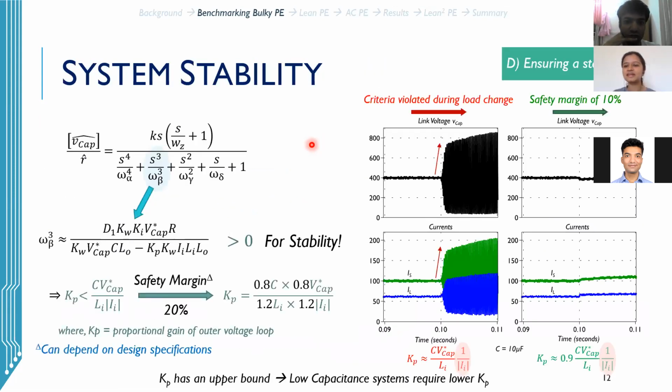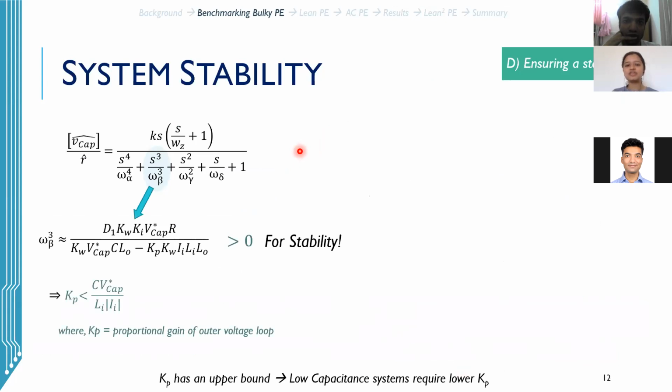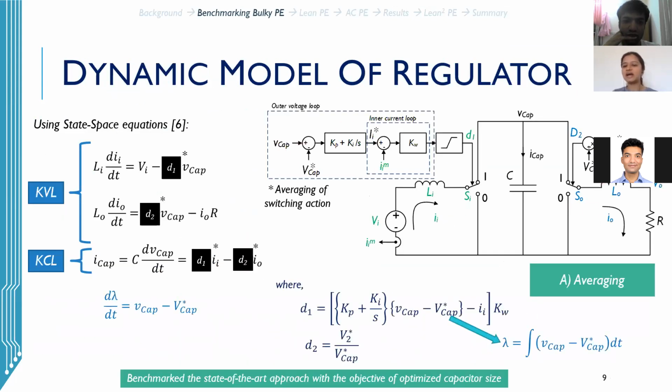So when you had indicated that there are two control loops, one on the input side and one on the output side, those control loops have already been stabilized and designed for stable operation, right? So this is the architecture that we have. We have a hierarchical control loop, but it is only for the input duty ratio. Correct. For the output duty ratio, we base it on a command. Yes. Correct. So in this architecture, the fundamental assumption is that the input functions independently of the output duty ratio. The output stage entirely is going to be reflected as a single resistive load, equivalently speaking.